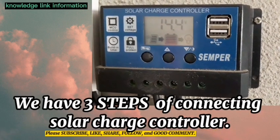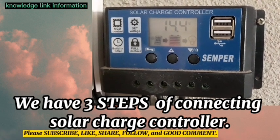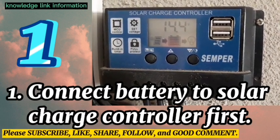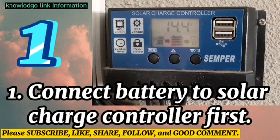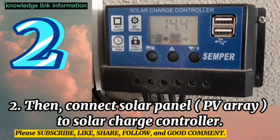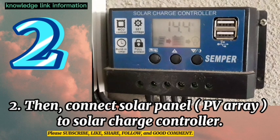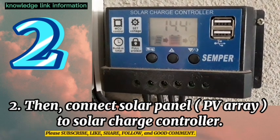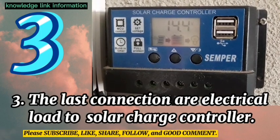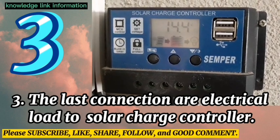We have 3 steps of connecting the solar charge controller. Number 1. First is to connect the battery to the solar charge controller. Number 2. Then, connect the solar panel PV array to the solar charge controller. Number 3. The last connection is the electrical load to the solar charge controller.